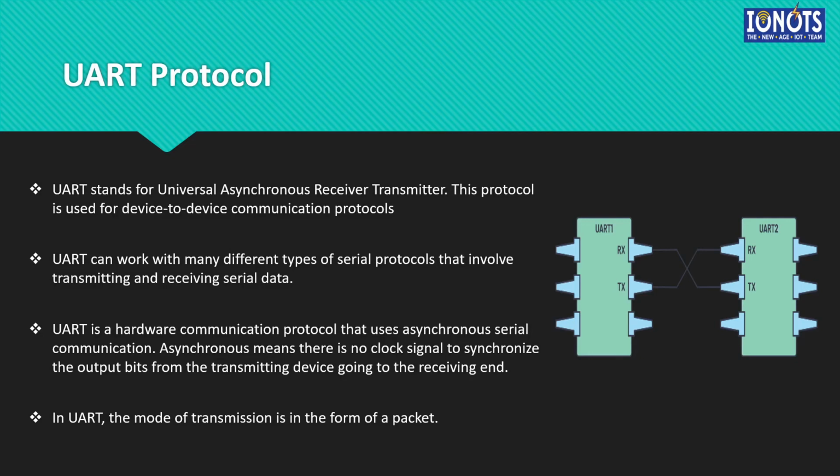Okay, so asynchronous doesn't mean that the device itself cannot have a clock. That is not the idea we want to propagate. The idea is that there will never be a common clock between them in order to synchronize.